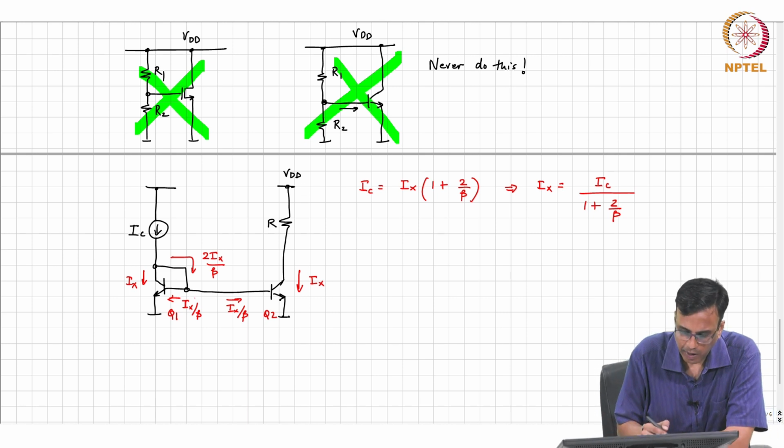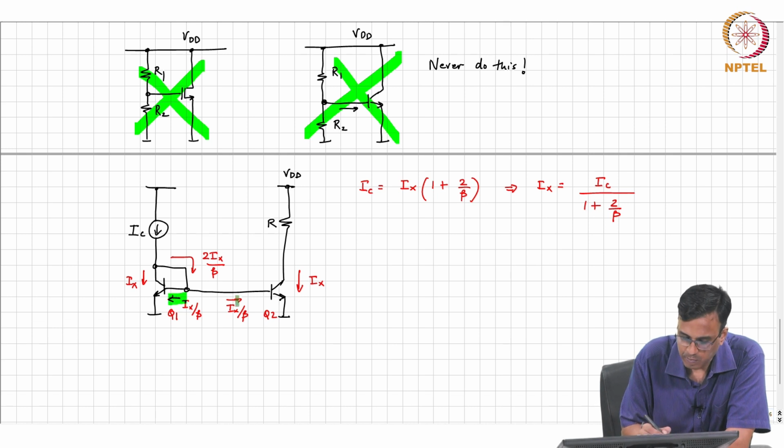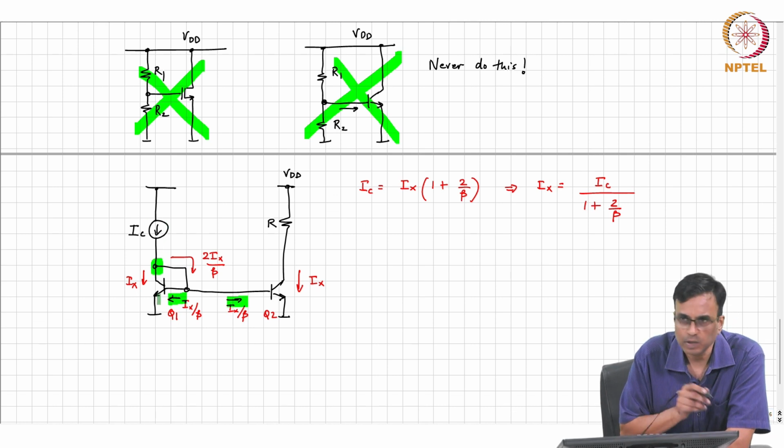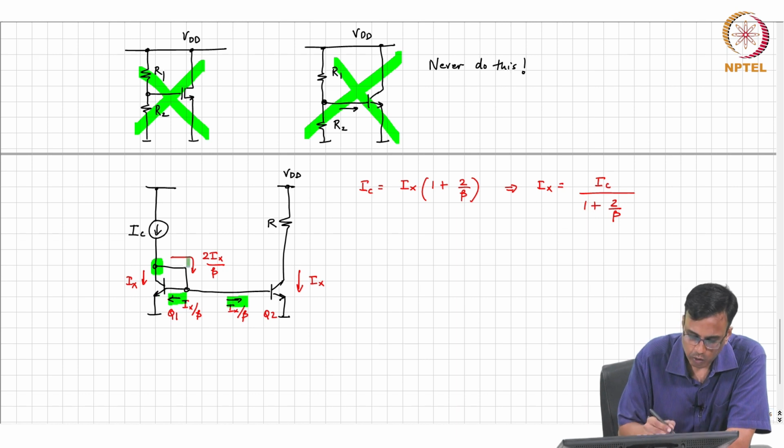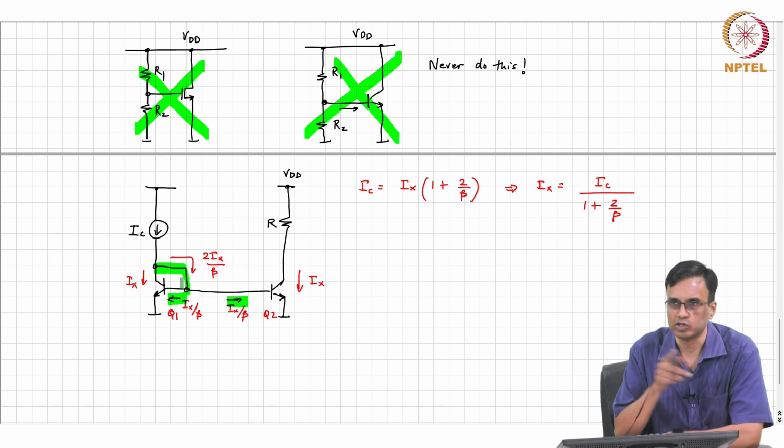Well, you can't avoid these base currents. These base currents can't be avoided, right? But the problem is that base current is getting subtracted out of IC. That is the problem, correct. So, what is this short doing actually, this base emitter, collector base short? What is its job?